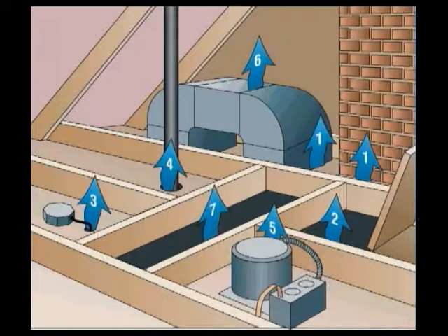In the winter, the house can act as a chimney as its warm air rises and competes with the appliance vent. This is especially a problem with tall houses that have a high percentage of their leaks in the attic floor. As you can see, there are a great many variables that affect draft for Category 1 appliances. It's not uncommon to find many negative factors working together to create frequent spillage or backdrafting situations. In fact, many if not most appliances will spill for a few minutes on startup until the chimney gets hot enough and draft gets strong enough to carry out all the combustion byproducts. We'll go into how to test draft and diagnose and improve many of the above variables in more detail in subsequent videos in this series.